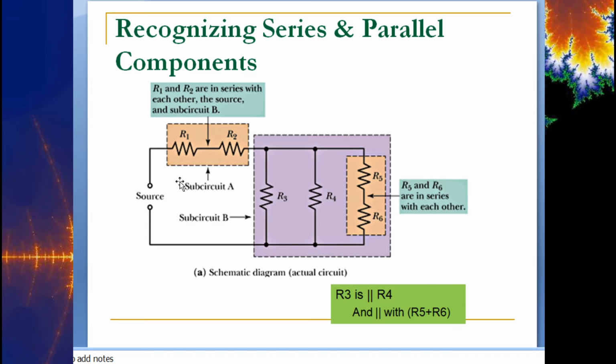So in this circuit here, we've definitely got some series and parallel resistance going on. Essentially what we're going to do is start farthest away from the source and try to reduce this network down to an essentially series circuit. This slide is calling these things sub-circuits. You don't really have to look at them as that, but really that's how they operate. So if I just look at these three branches, I realize there's something going on over here in this branch, but these three branches I notice are in parallel with each other. That's what you see in the purple.